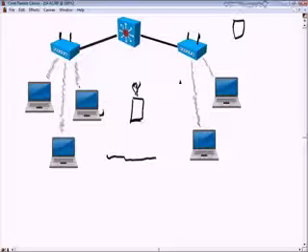Now, there are some rules for data transmission over RF, okay? If you have a higher data rate, you'll have a shorter range because the receiver needs a stronger signal with a better signal-to-noise ratio, SNR, to receive the information. If you have higher transmit power, that'll result in greater range. That's governed by the FCC.